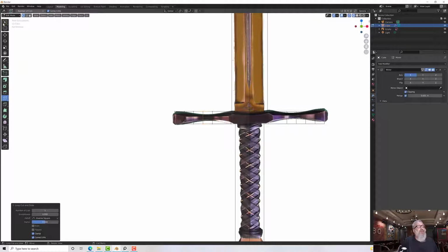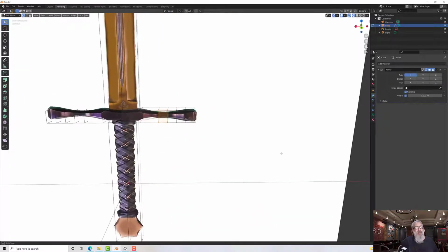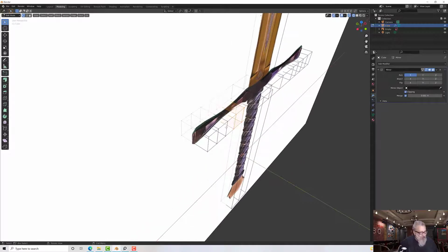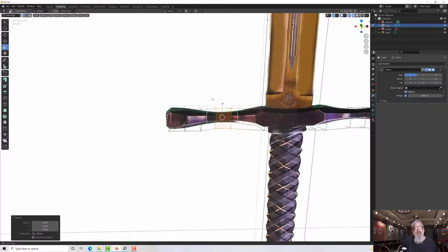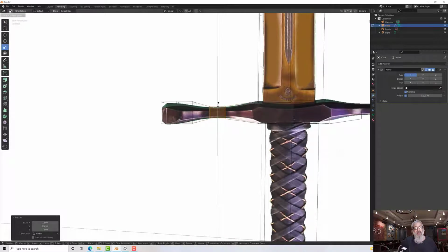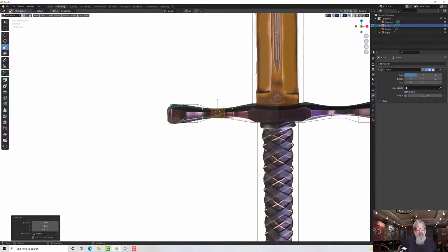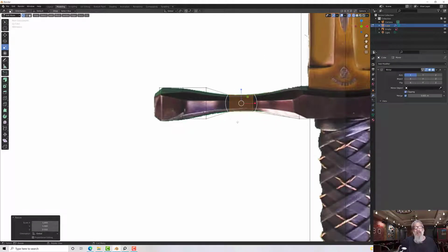And now if I go to select mode, we'll use the W key, I can left box click over that. I keep pressing that button and it hides my interface, it's driving me nuts. And let's rotate around and make sure I've got everything selected. And now I'm going to use the S key, the scale key, to just bring that in a bit. And then I use the blue to bring that down so it matches the front image. So you can see there that my top and my bottom is matching up.